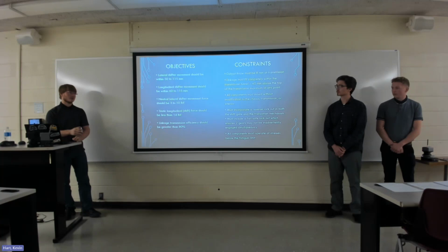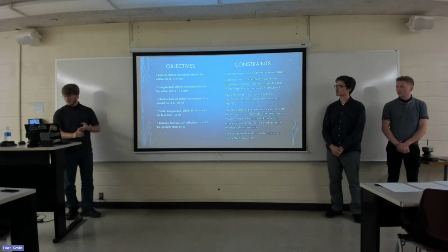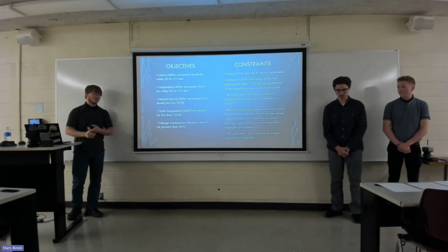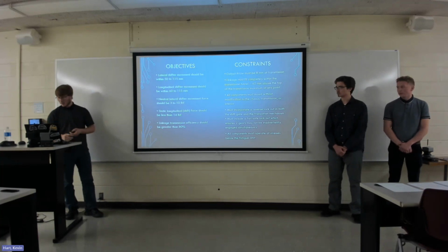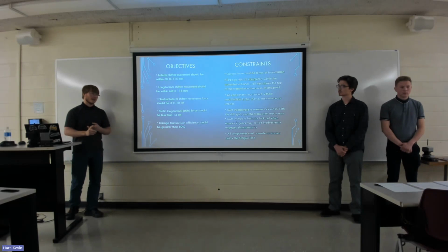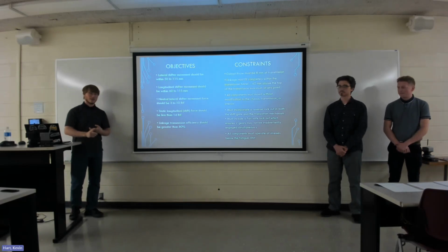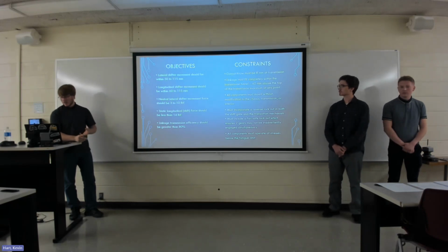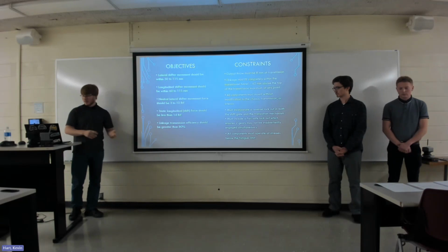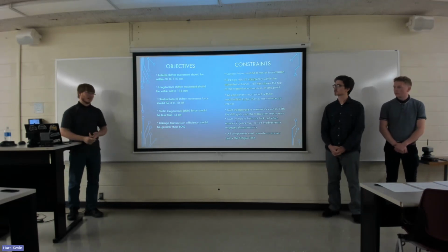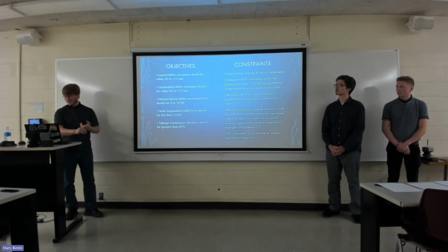All components must mount to the transmission, the chassis, and the interior without modification. We must incorporate a reverse lockout to prevent accidental engagement. And we must include a fail-safe lockout, which ensures that two gears can never be accidentally engaged at the same time, even if there was a single component failure of our system. Finally, our goal is to have all components operate within their fatigue limits for ideally infinite service life, but at least as long as possible.